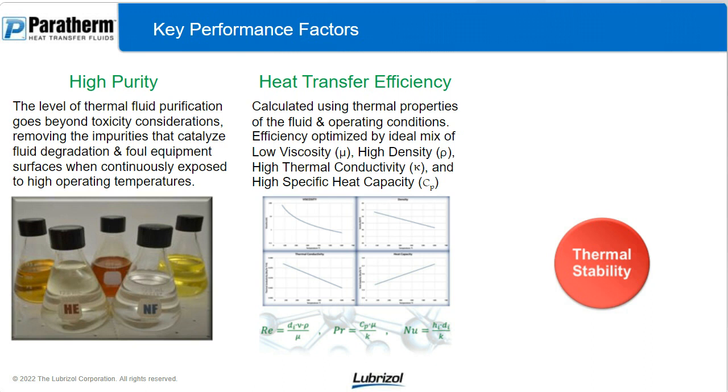In order for a fluid formulator or a fluid designer to actually design and create a new fluid, they would have to make sure that they tested around all of those factors to give you a more efficient fluid. So if the fluid supplier doesn't have that data available to you across the entire temperature range that you might be considering, the odds are that that fluid wasn't intended to be a heat transfer fluid to begin with, or a thermal fluid. So that's a good indicator. Make sure, insist on that data, see if they have it, use that as an indicator or qualifier if it's a reputable supplier or not.